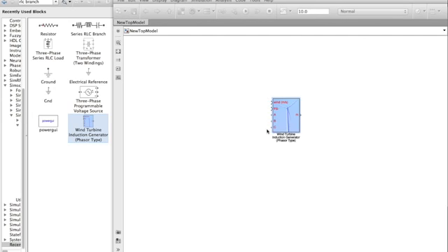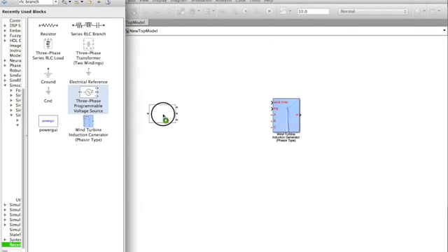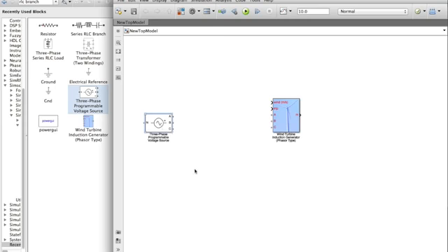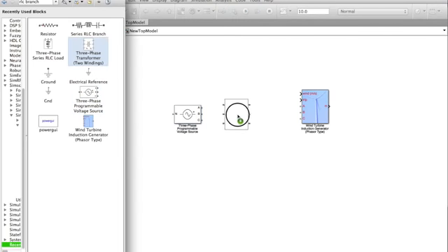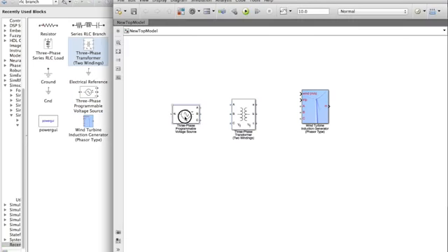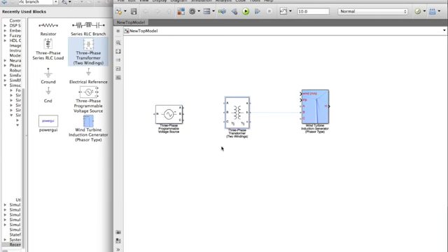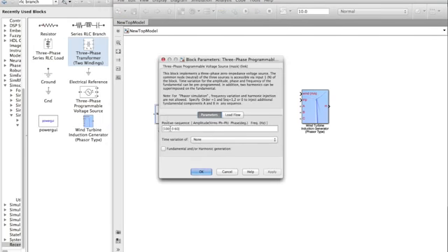Now we will create the reactive power source. First, we'll use the three-phase programmable voltage source to provide the three-phase power. It has the A, B, and C ports and the 0 for ground. We'll connect it to a transformer, as it will be done in real life, because the voltage source uses a high voltage. We'll set it to 25 kilovolts.